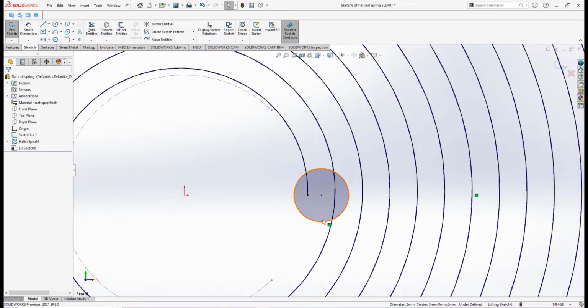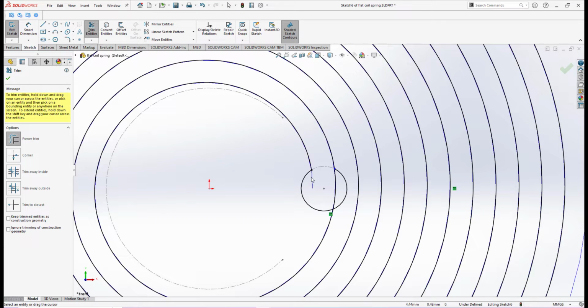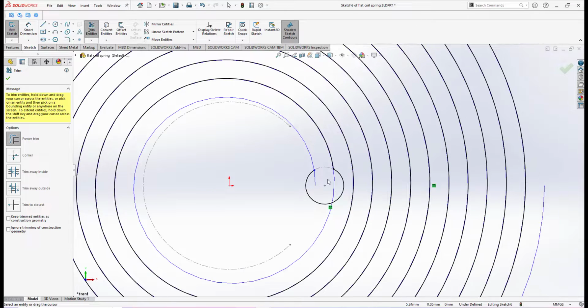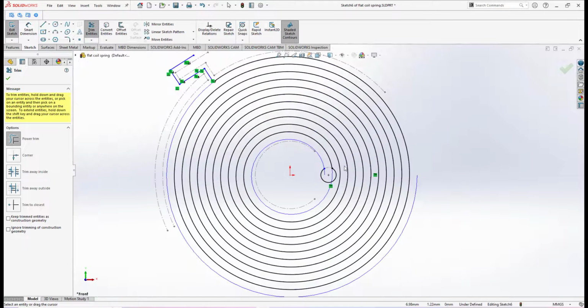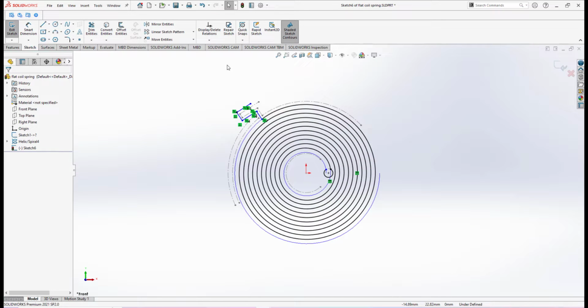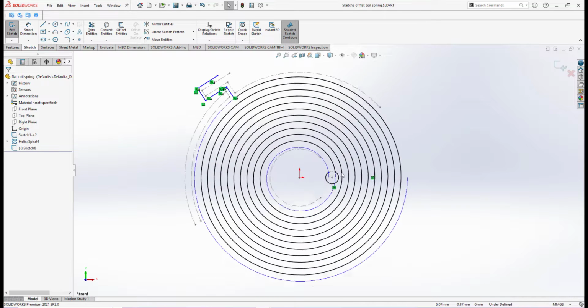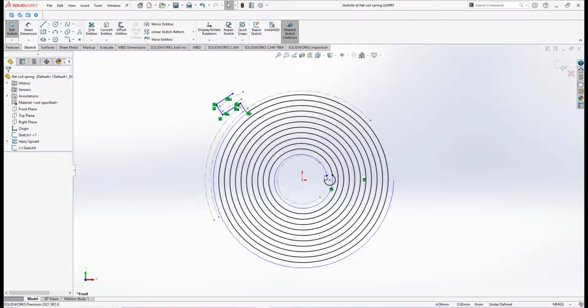It means I have to stop my spiral up until this point. I need to trim it, so I have a boundary. So I will trim this portion, and also this part, and this part, and this part. So we have a hook shape there for our spiral curve. Okay, let me save my file first, and I'm now in sketch 6.